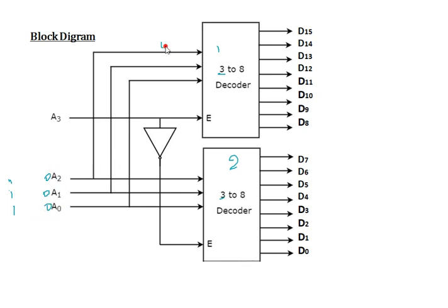So I am placing 0 0 0 here and again here 0 0 0. Observe A3 is the input for enable. Consider A3 always 1. So 1 is given as it is here and it is not yet, so it is 0. 0 0 0 0, all zeros, means 0 is my output.